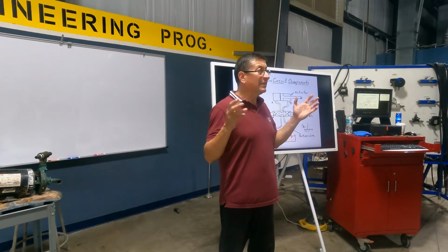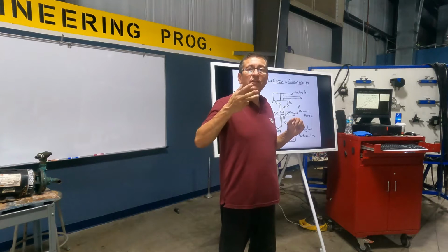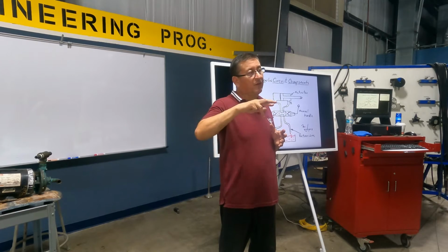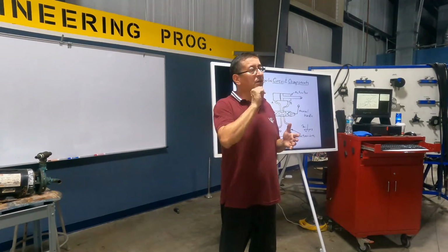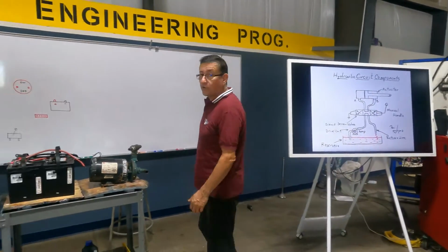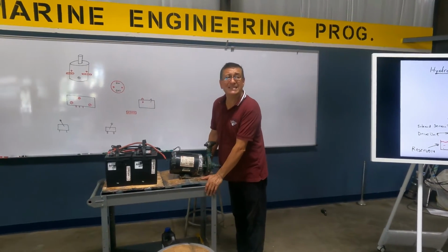Remember the three-phase motors? You only need to switch the lines of two phases, and immediately the rotation is reversed. Okay, we are going to start with the process to reverse the rotation in DC motors.